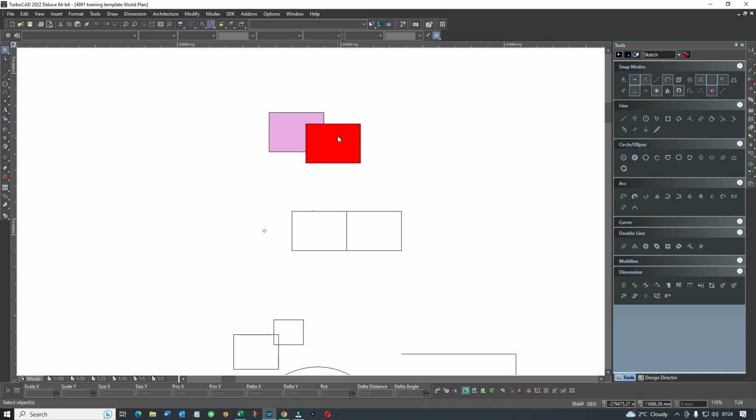now you've got to listen for this. Hold down Shift. Hold down Page Down. It would help if I selected the item first. So we go Shift, Page Down. And as you can see, the draw order has changed. Now it's very important when you're using fill tools, and let's assume you're filling something but you want it to go below, and this will apply to anything you're doing. Shift, Page Down changes the draw order. Just select it, Shift, Page Down.